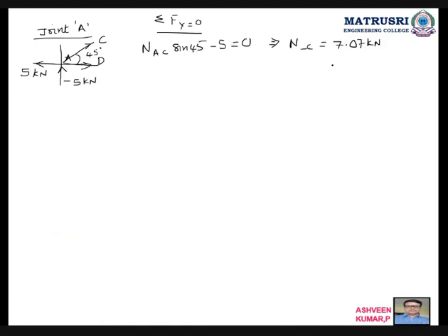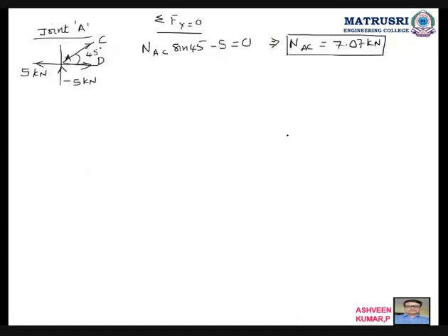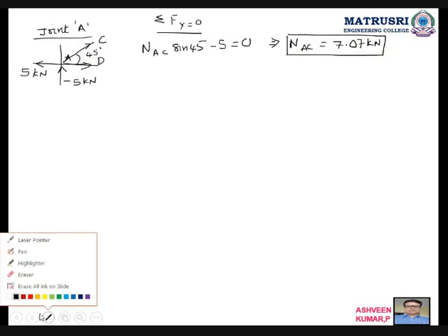Then what is the unit load? I want to apply a unit load, that is one load, where I require the deflection. Where is it asking deflection? It is asking deflection at C, the vertical deflection at C. Therefore, I will draw the figure here, applying one.